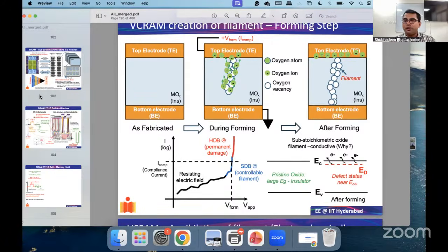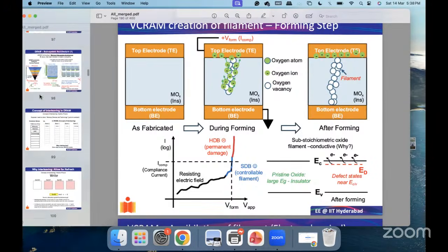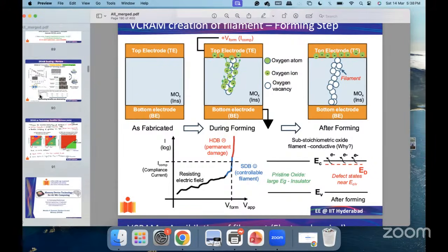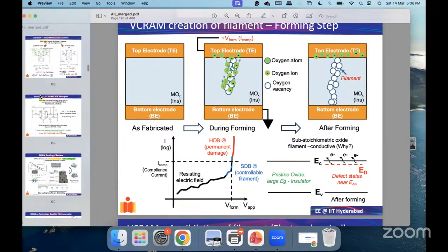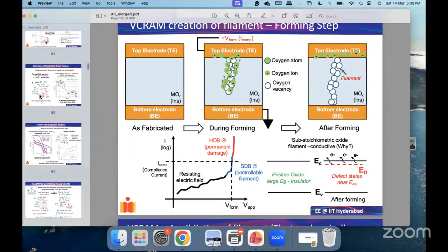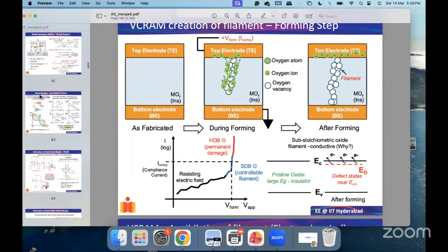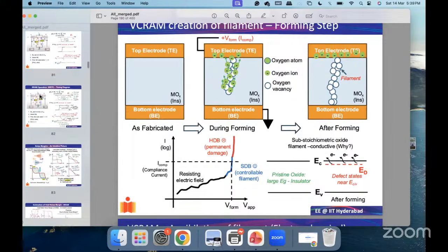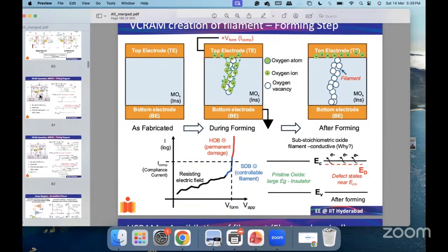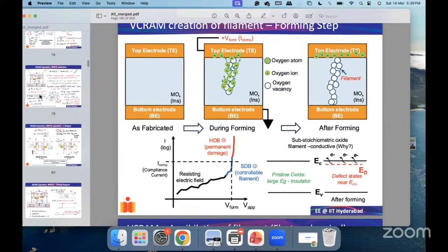If I explain my terminology, if I say FS, that means the NMOS is in the fast state and the PMOS is in the slow state. So VT-wise, the NMOS VT would be lower because it is in the faster state, and the PMOS is in the slower state because its VT would be high. In fabrication, you have these FS, SF corners.